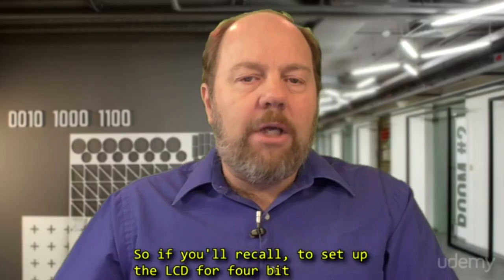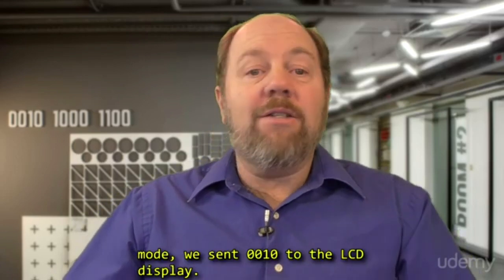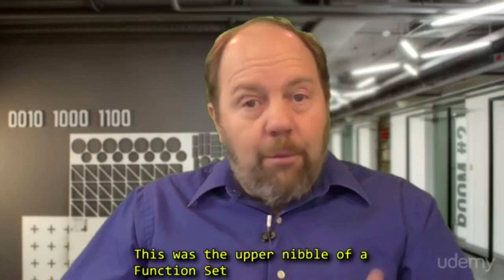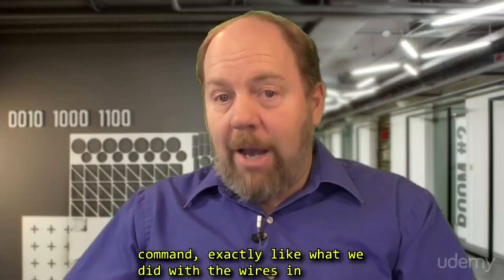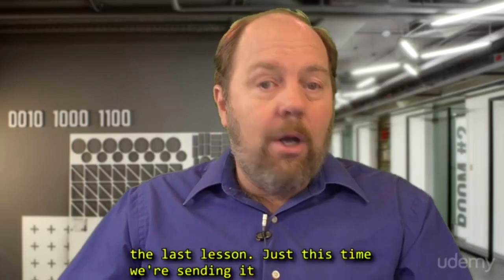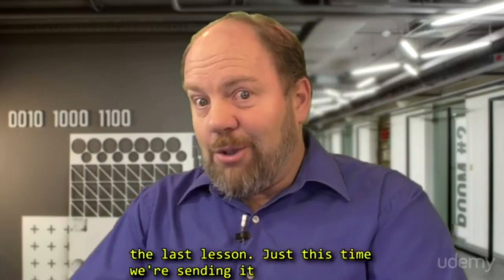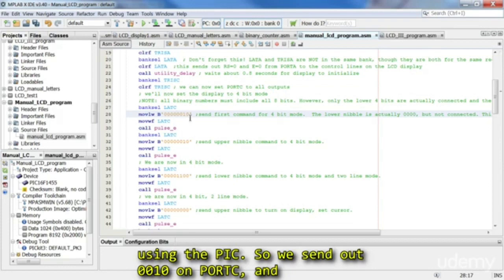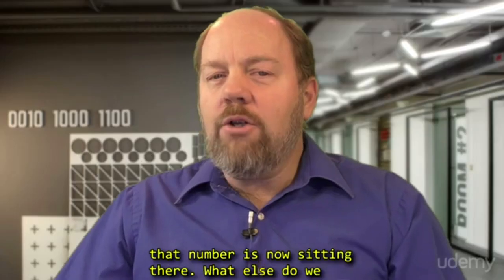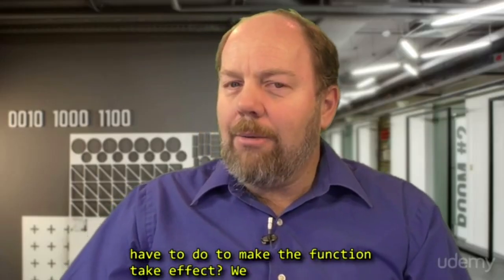So if you recall, to set up the LCD for 4-bit mode, we sent 0010 to the LCD display. This was the upper nibble of a function set command, exactly like what we did with the wires in the last section. Just this time, we're sending it using the PIC. So we send out 0010 on port C, and that number is now sitting there. So what else do we have to do to make the function take effect?